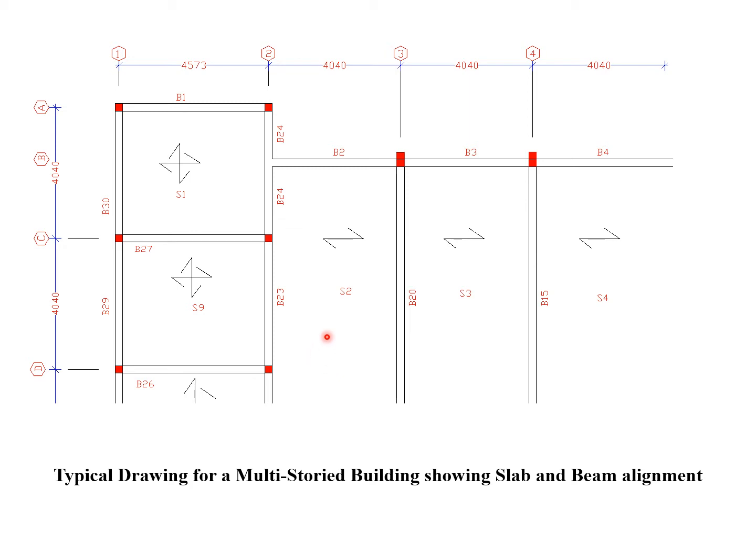So to recollect, each corner will have a column. Then the columns will be connected by means of beams. If the span increases, or if I have a concentrated load coming from a brick wall to the slabs, then a beam should be spanned. At the end of a beam, there should be one column. Depending upon the span of my beam, the depth will increase.